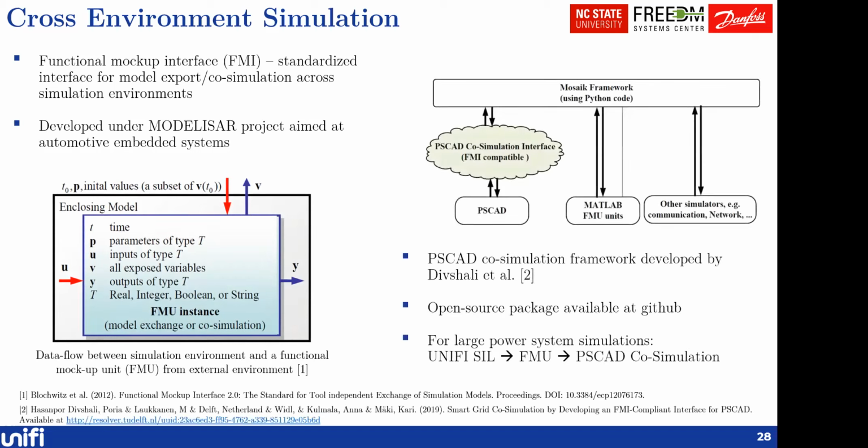And I found a pretty nice example which actually applies to exactly what we are trying to do. This is work that was done by a group at Delft University of Technology. They exported their power electronics controller model from the MATLAB environment with a standardized interface, which is this FMI, functional mockup interface. And the model that they export is called an FMU, functional mockup unit. And this can be completely black box.